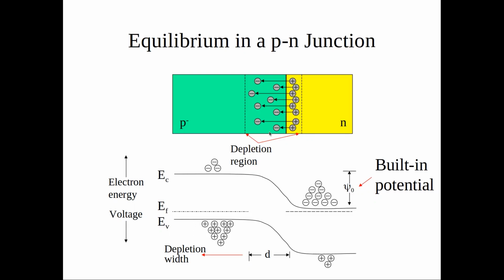Because in this case, the N-type, you can see it also from here, had a higher concentration of donors than the concentration of acceptors. There was an imbalance in the P and the N, which actually reflects the real way semiconductors are made. So it really depends. If you have exactly the same concentration of donors and acceptors, it would be perfectly symmetrical. But because in practice it's not, we also made the drawing more realistic in that respect.